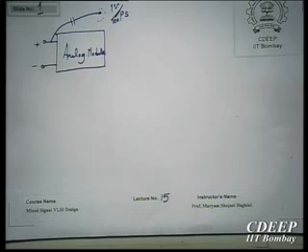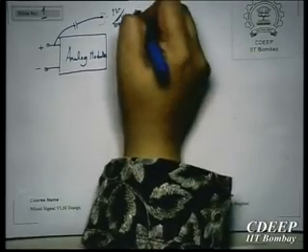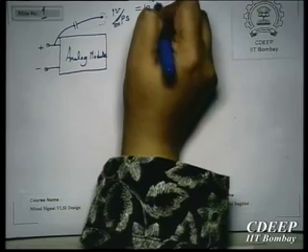So this is a typical value, right? In 0.1 nanosecond, I have 1 volt change of the amplitude. It's a very typical switching for a high-speed digital circuit. So this means a transition of 10 to the power 10 volts per second.